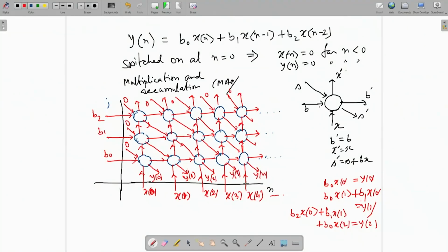Okay. So, this is a DG, dependence graph. You see all connections are local. Whatever is the pattern in one place, you design a mask for it. And when you design the IC, just put the mask here, here, here, and all the incoming outgoing edges join together and this very regular structure comes. There is nothing haphazard in this structure, nothing irregular. That is why it is very, very useful, very good for VLSI design.